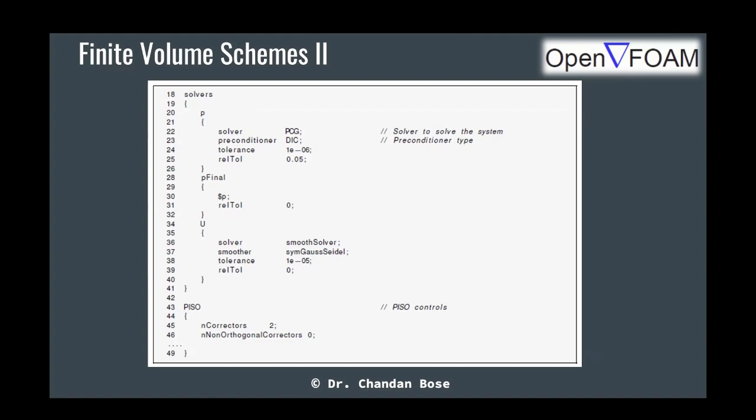While we learn programming, there is a way to find out whether the syntax is correct or not. It is like that. Because OpenFOAM is written in C++, whatever is applicable to C++ is also applicable to this. So it is case sensitive, and you have to give the correct name of the solver or anything that you want. Otherwise, it will say that the solver is not found.